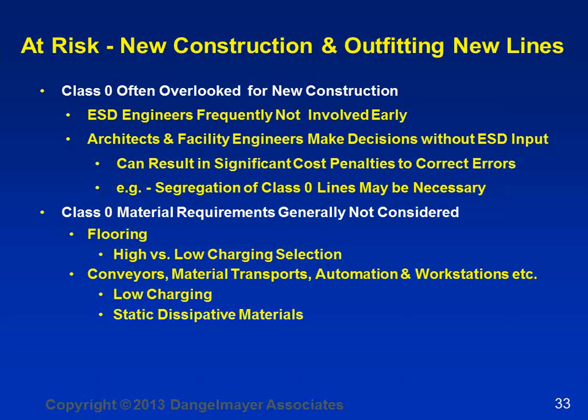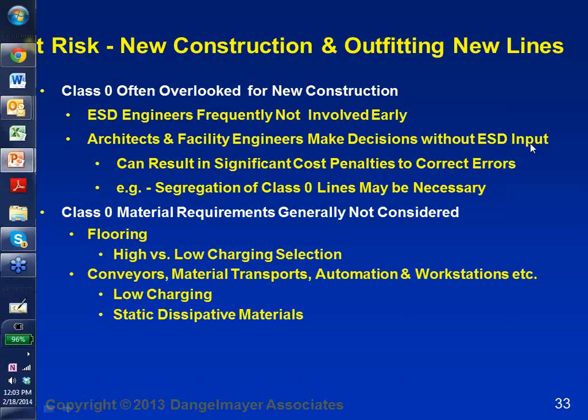We redid a major area at AT&T with conductive vinyl and had people complaining frequently about getting zapped in the area because of the vinyl. They were walking in the area in non-ESD shoes. We didn't require everyone to be grounded. Only those that worked in standing operations needed ESD footwear. And those that had regular street shoes were getting zapped left and right.